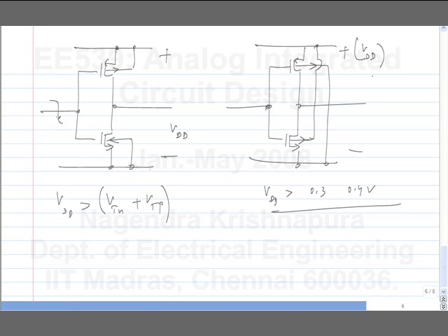Looks like a typo. So you connect the bulks opposite to what you normally connect them to. And this is a digital circuit. There have been op-amps also made for 0.5 volt supply operation in the same technology that you are using to simulate. If you do conventional circuitry, I don't think you will be able to make circuits with 0.5 volt supply in your 0.18 micron technology, whereas there are op-amps that are made by using the bulk also as an input terminal.